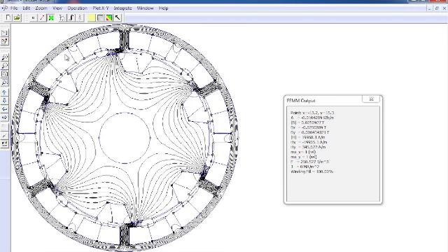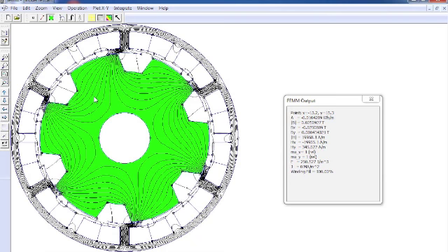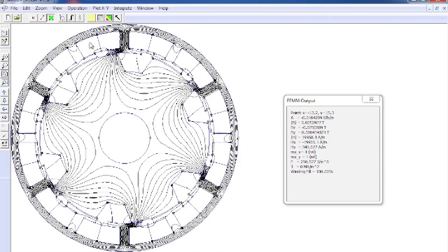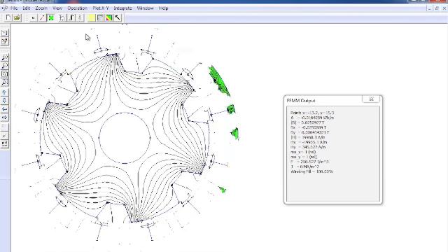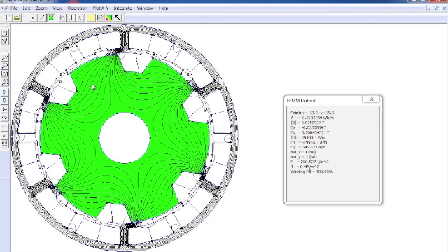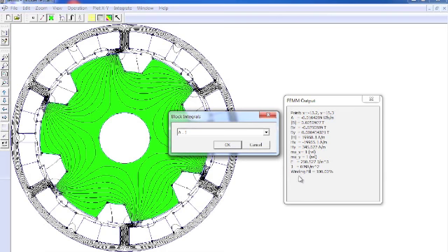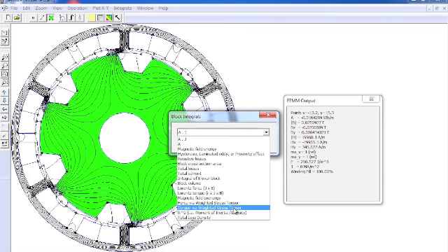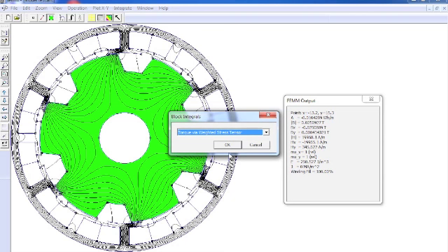But let's just go ahead and select a block, which counts as any enclosed space. So for instance, the rotor is a block, this winding area is a block, the stator makes up a block, the air gap makes up a single block. So let's go ahead and select the rotor. Now we need to perform a torque via weighted stress tensor integral over this selected block.